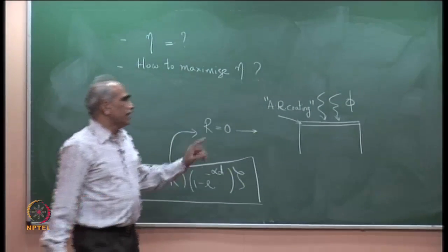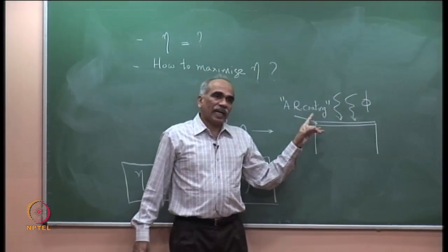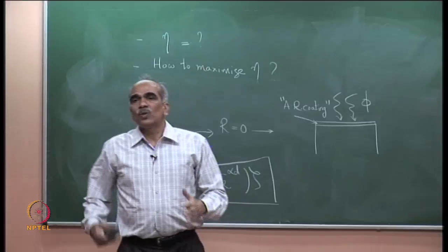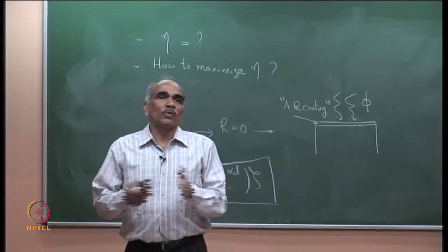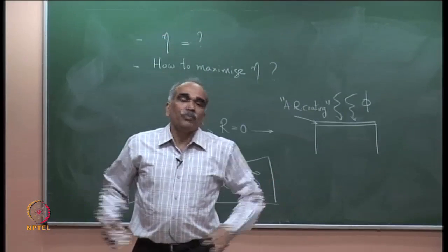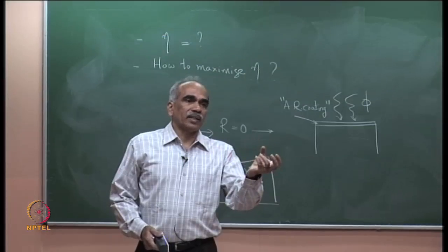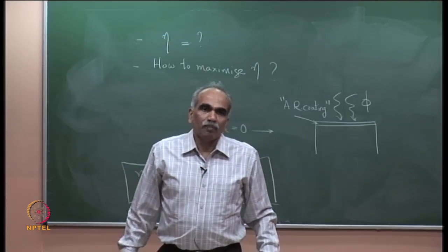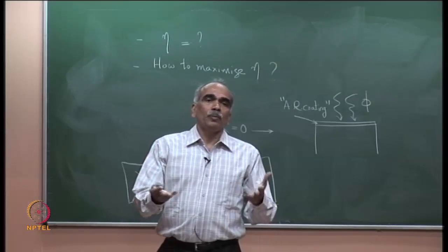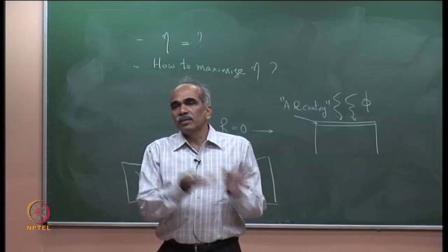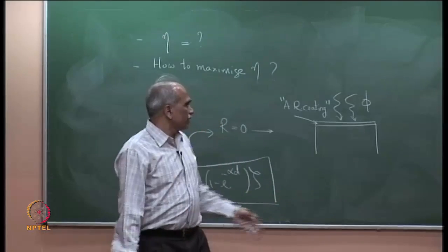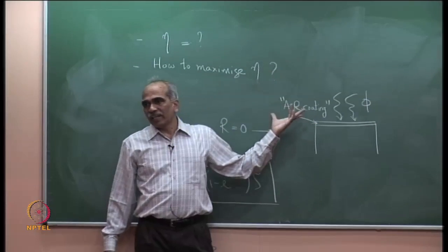Of course, in general you can make anti-reflection coatings at one particular wavelength. It is not possible to make anti-reflection for all wavelengths. If you are using a general photodetector with a power meter for a general purpose measurement, you may measure the visible region and the IR region, a range of wavelengths, and in such cases it is not possible to make an AR coating.